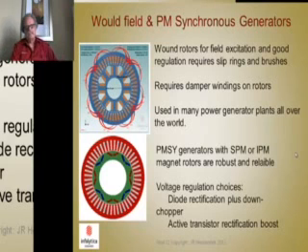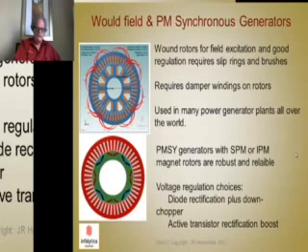The bottom picture there shows the Toyota IPM for the Prius. It's not very common to use IPMs with a lot of saliency. It's not common to use those as permanent magnet generators because they don't make good generators. Their linearity is too poor. The reluctance torque, the reluctance aspect. It's better to have the magnets for a good permanent magnet generator.